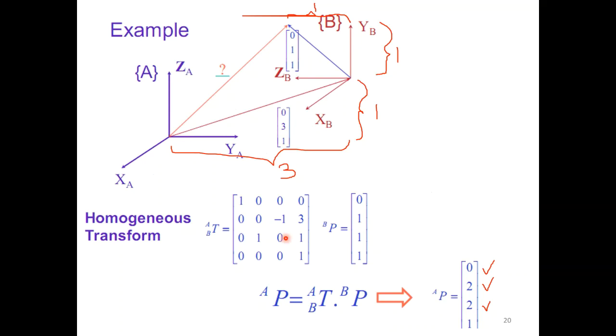So if the rotation is around the y-axis or z-axis, and a non-90 angle, any angle, plus or minus, you should be able to tell me for any angle, say alpha, beta, gamma, what is the format, the structure, for the rotation matrix?